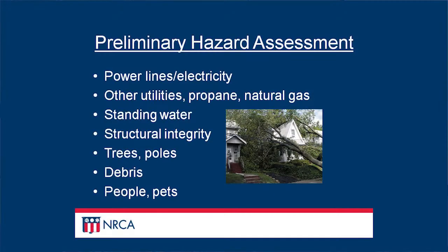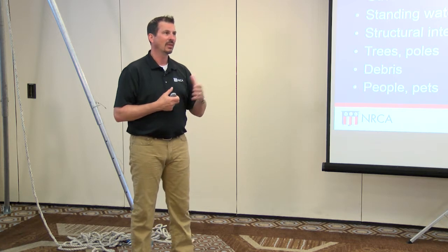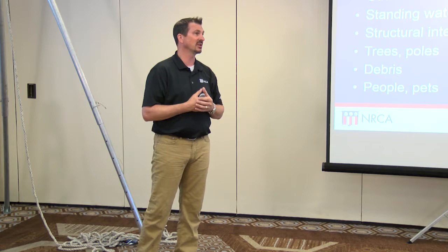Look for standing water, because of course if we have standing water at a job site, we know that the ground structure may not be capable of withstanding loads or may change during the course of our job. Structural integrity, that kind of goes without saying. We have to look at the decking, both top and bottom, to determine if there's any damage. Okay, and how do we do that? Well, it's by actually getting out there and doing the investigation ourselves.